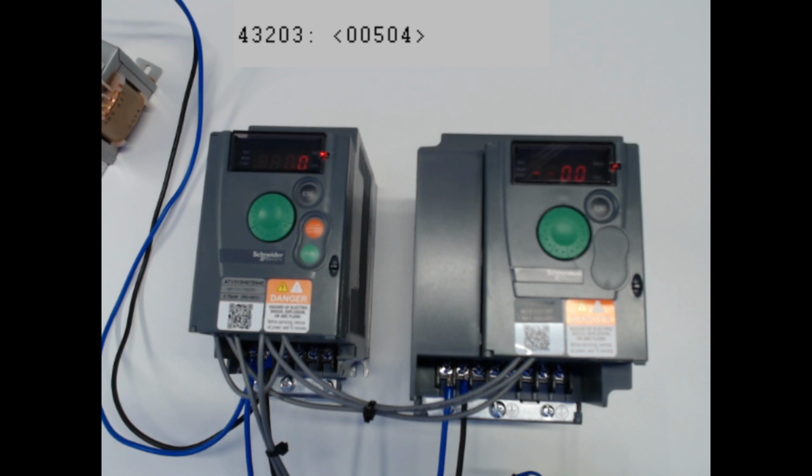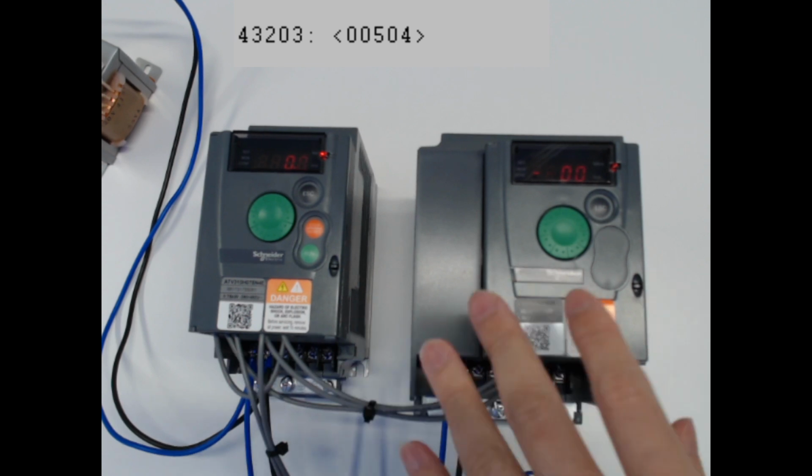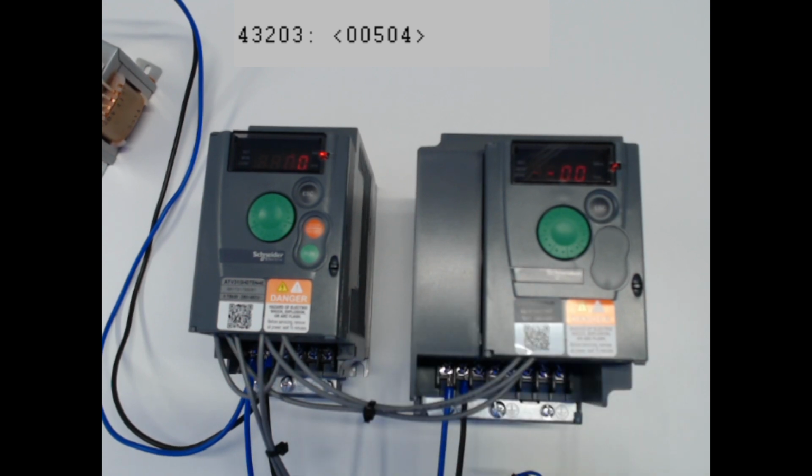Okay, so this is what happens in a very, very straightforward configuration. There is no changeover here. There's just a simple one drive bringing another drive along. So it's not ideal, but it serves a purpose for today's demonstration. If you want to try to design it in a panel with switchovers and things like that, things will get complicated very, very fast. So always think about what happens if the master trips and things like that.